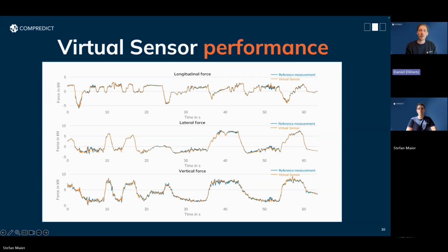We also calculate a damage value, or as we call it, a duty value, and relative damage difference using rainflow counting. But also, and this is especially relevant if we are talking about sports cars, the peaks are one of the most relevant things that a virtual sensor has to deliver. So we obviously take these peak evaluations into account as well.